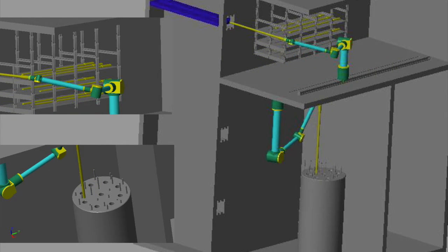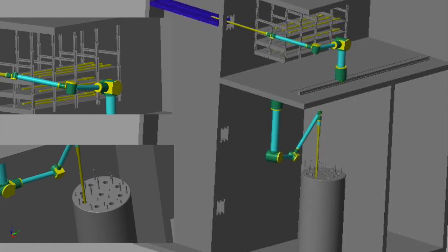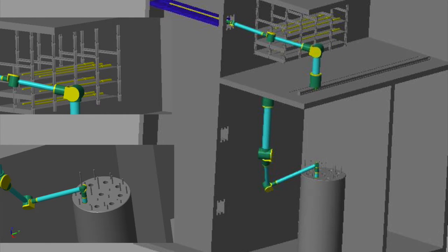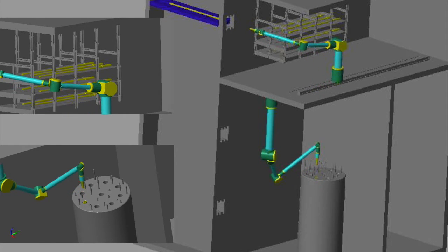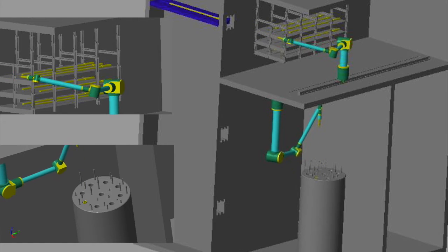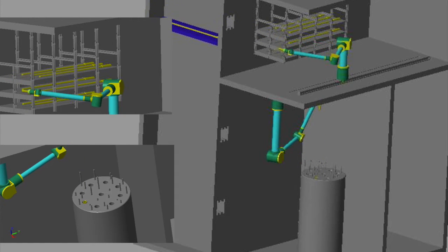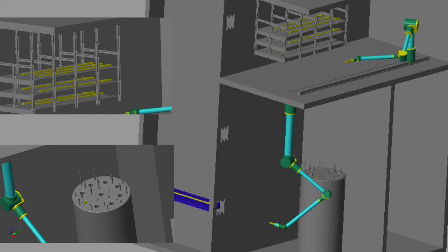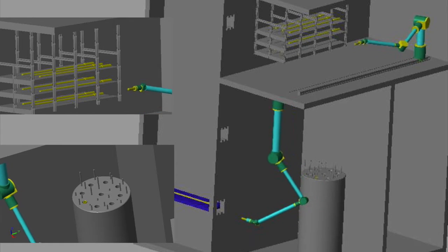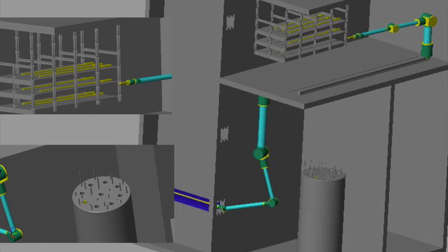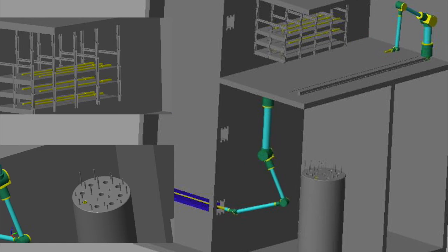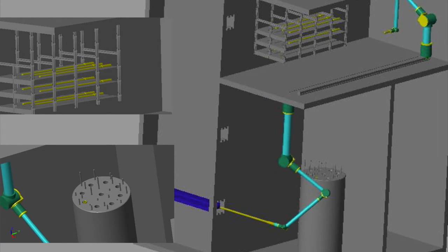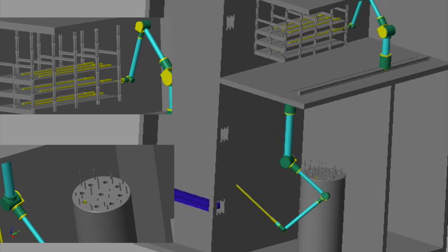In order to use the robotics toolbox functions ikine and ikunc, a robot object had to be created with the proper DH parameters and joint limits. The function ikine utilized the robot object as an input as well as the end effector position and orientation. This was passed as a homogeneous transform. Additional inputs were a guess for the orientation and a mask, which specifies any translations and orientations that do not need to be solved.